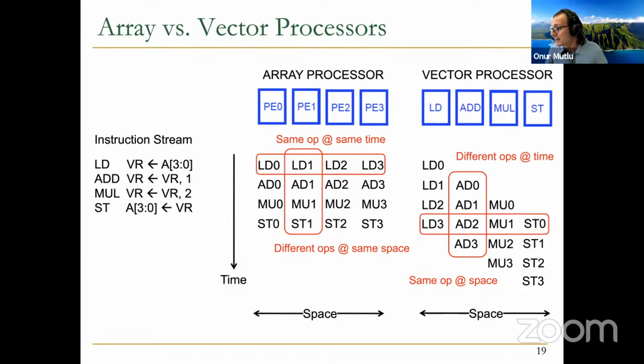Okay, so are vector registers a distinct part of the hardware, or are they general purpose registers? So basically, these could be general purpose registers, sure. In a vector processor, in a SIMD processor, it could be a general purpose register. You could have both types of registers, as we will see also, because this is very good at executing single instruction, multiple data operations, but you could also have another part of your processor that has more MIPS-like registers or scalar registers, right?